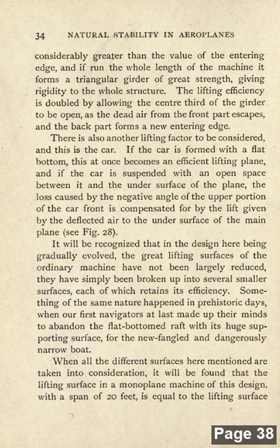There is also another lifting factor to be considered, and this is the car. If the car is formed with a flat bottom, it becomes an efficient lifting plane, and if the car is suspended with an open space between it and the under surface of the plane, the loss caused by the negative angle of the front portion of the car is compensated for by lift given by the deflected air on the under surface of the main plane. See Fig. 28.